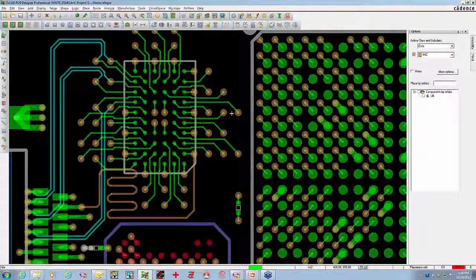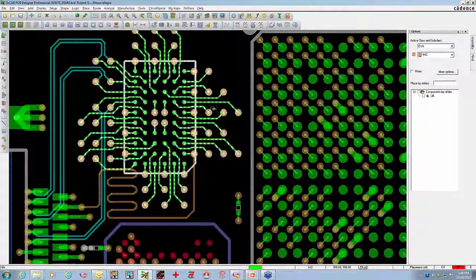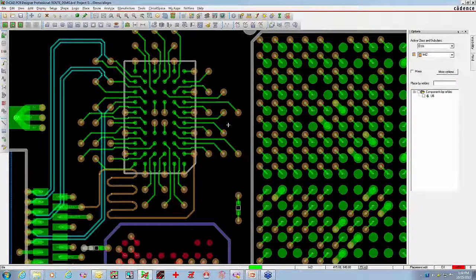And the key is, because of the channel space in between each of these vias, I now allow the Autorouter to effectively get to those routing points very easily, and I don't cut off any route channels in the process. So that's the whole point of these complex parts. We can actually build a pin escape scheme that's going to work for the Autorouter.